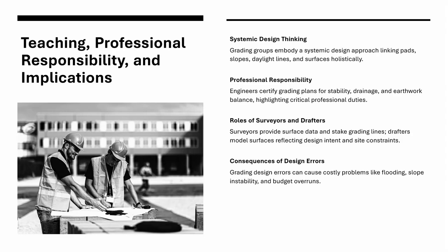And it's also worth noting that grading is one of the areas where professional responsibility is most visible. Engineers sign and seal grading plans, certifying that slopes are stable, that drainage is adequate, and that our cut-fill balances are reasonable. Surveyors often provide the existing surfaces and may also stake out grading lines in the field.